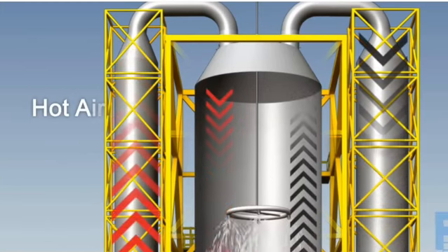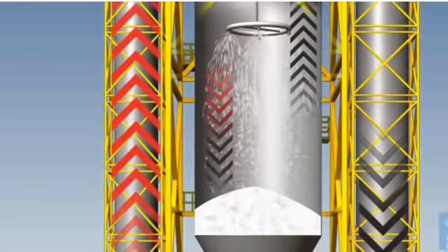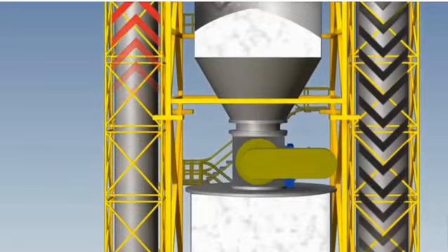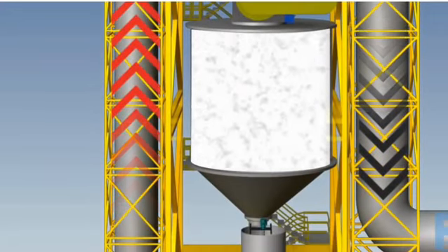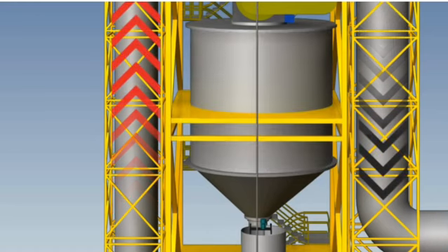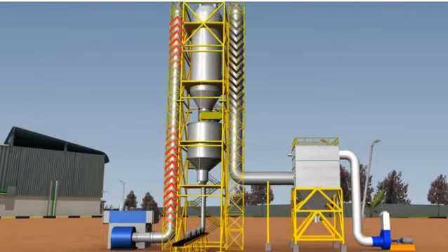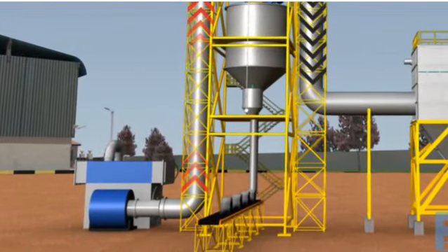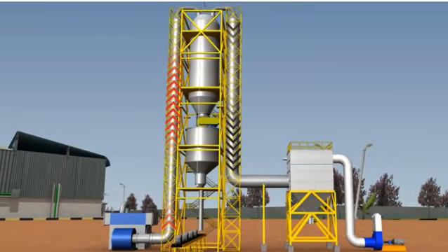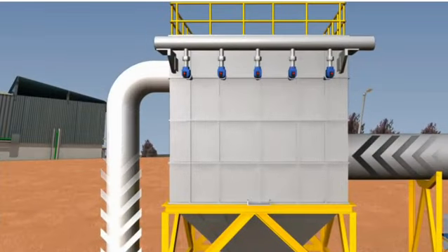In conclusion, spray drying is a remarkable innovation in food technology. It transforms liquids into powders that are convenient, lightweight, long-lasting, and nutrient-preserving. The next time you use milk powder, add fruit powder to a smoothie, or use egg powder in baking, remember the incredible journey the liquid underwent: from feed preparation, atomization, rapid hot air drying, to separation and collection.